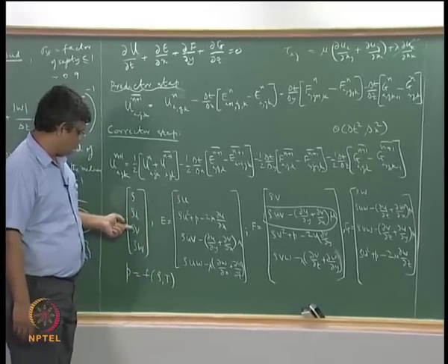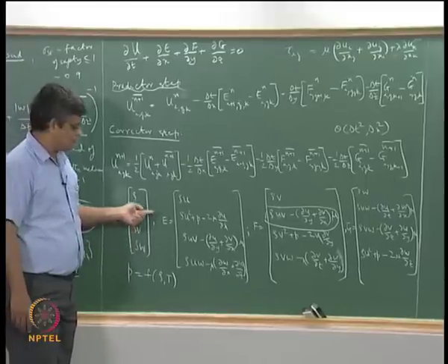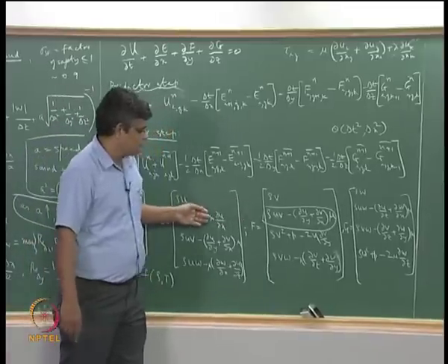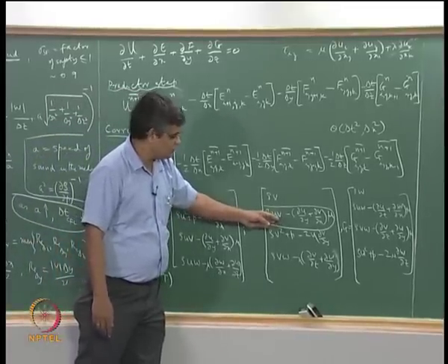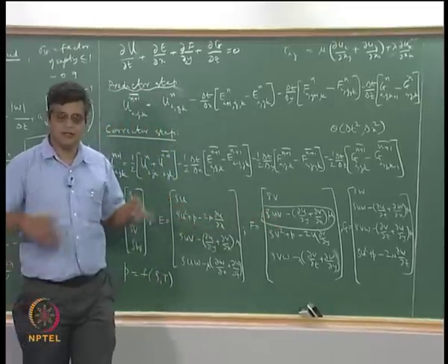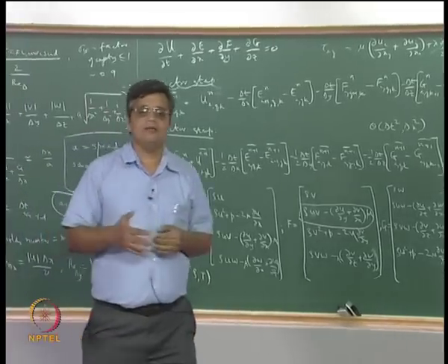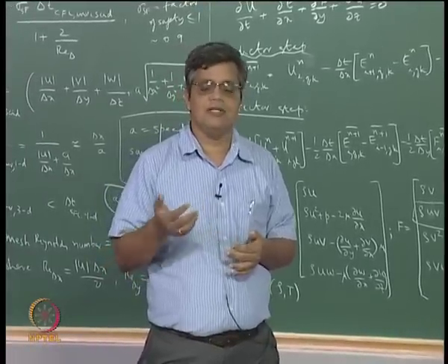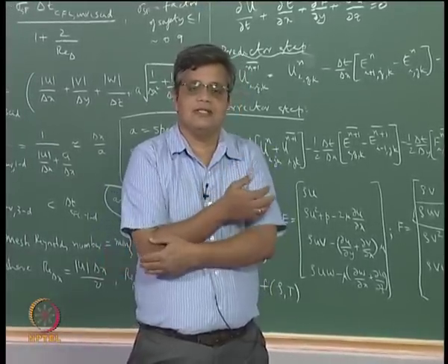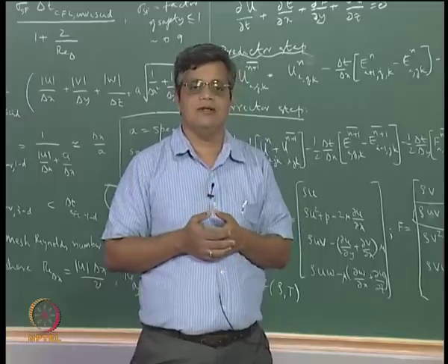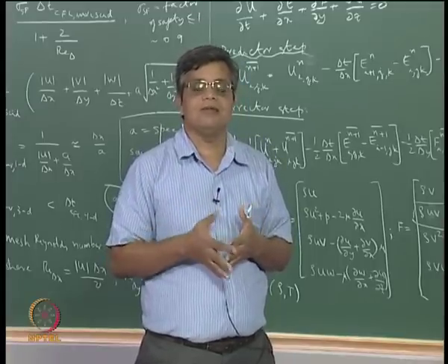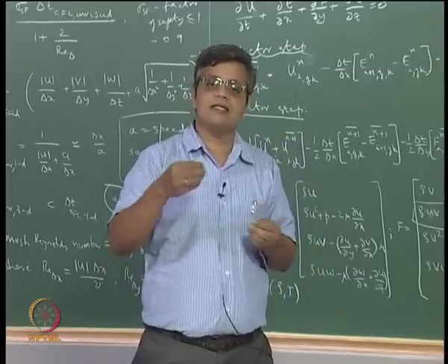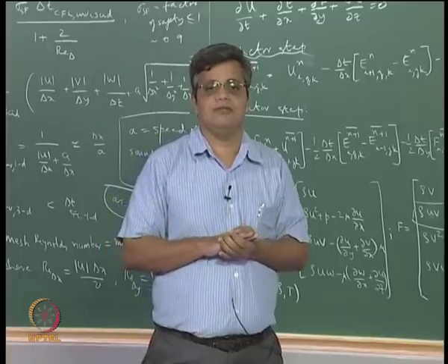When you go to the evaluation of v and w equations, you are carrying forward a large time error in the evaluation of u. Since the evaluation of u also affects the evaluation of v and w, the coupled nature does not allow you to have too large time steps. So you can typically have only maybe 5 times or 10 times the explicit limit for an implicit calculation, and that arises primarily because of the intercoupling of the Navier-Stokes equations.